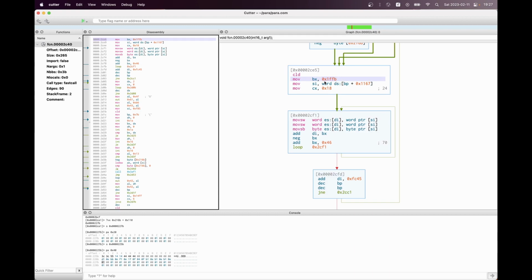That value 1FFB is really close to 2000 in hexadecimal. Actually, 1FFB is just 5 less than 2000. And these 5 less is something that I would expect, because it should be something that puts us at the beginning of the character on the next line.